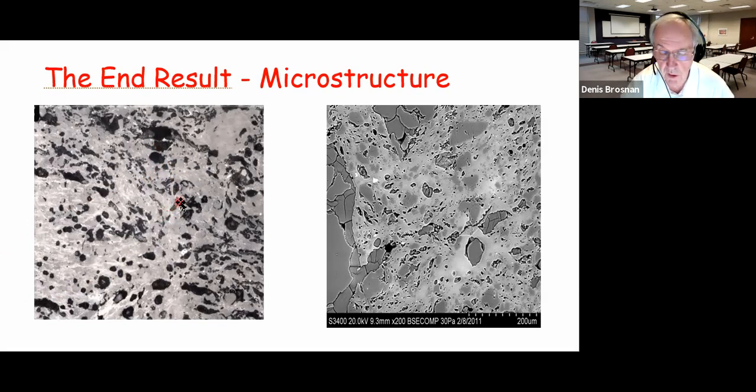And that's why bricks in Roman structures in Western Europe, particularly where there's freezing and thawing potential, are still looking very good. The Romans knew that they needed to fire the bricks to very low water absorption, very low porosity to make them durable. Imagine that, knowing that 1,000 years ago.